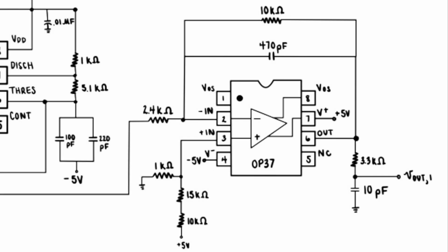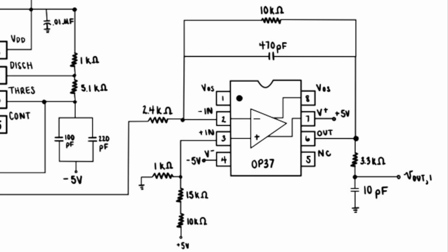However, during initial testing, it was revealed that the 5.2 kiloohm resistor introduced noise and instability into the triangle wave output. So to address this, I replaced that resistor with a potentiometer, and this allowed me to do some fine adjustment in resistance. And the tuning determined that a 2.4 kiloohm resistor produced a significantly clearer and more stable triangle wave. So let's identify the other components that are a part of this integrator.